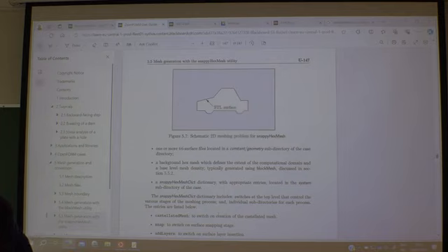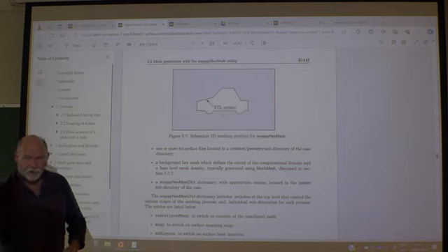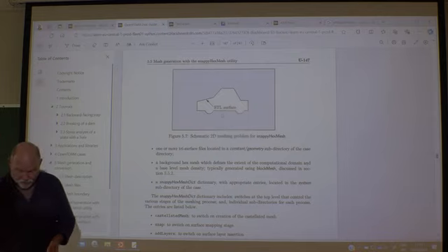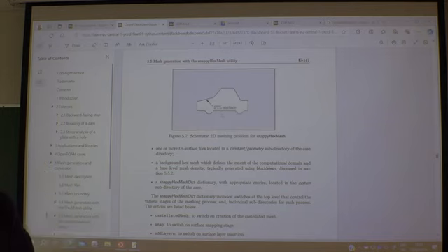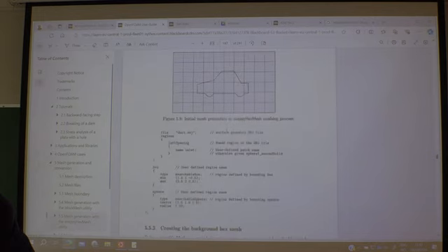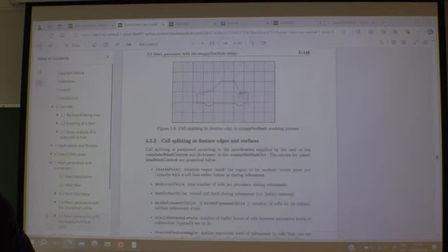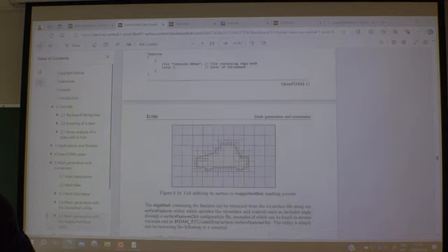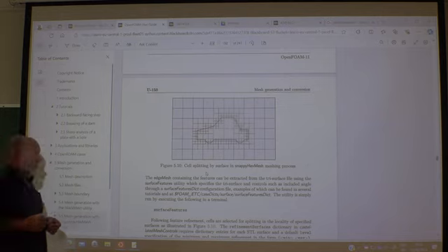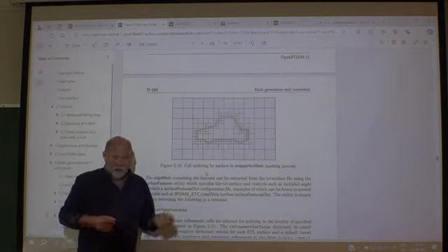Well, you need an STL surface. STL is a file format that is not just an image, but also some logical vector graphics. So you need such an image first, and then smack it onto the background mesh, and then you have several steps to finally end up with a good mesh. So there are several stages within snappyHexMesh that have to be performed.